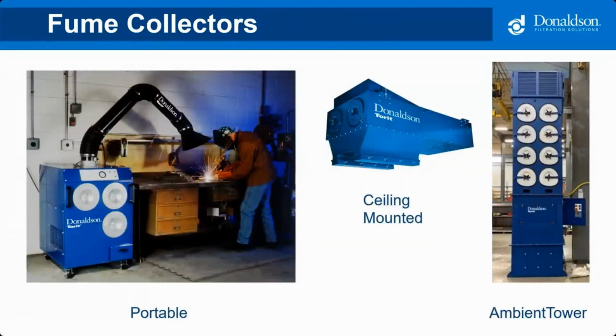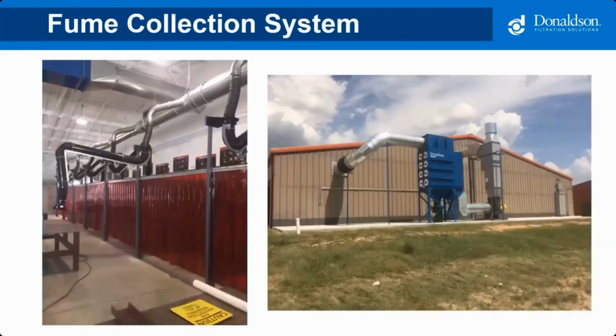There are a lot of options when it comes to fume collection. Here are a few examples of portable fume collectors for occasional welding, ceiling mounting collectors, and tower style collectors. So if there is limited to no floor space available, or if you have overhead cranes that don't allow you to use any ductwork, you still have options available. Here's an example of a large central weld fume collector. It is located outdoors, but it is attached inside to welding booths and extraction arms.